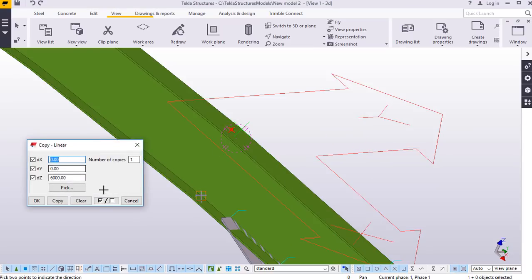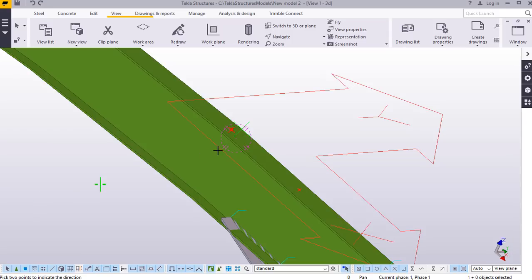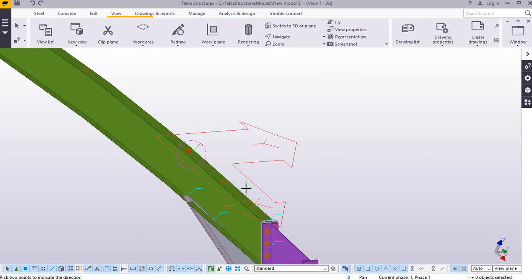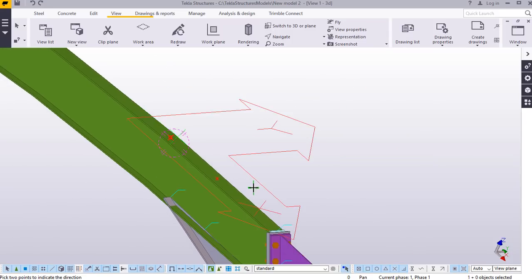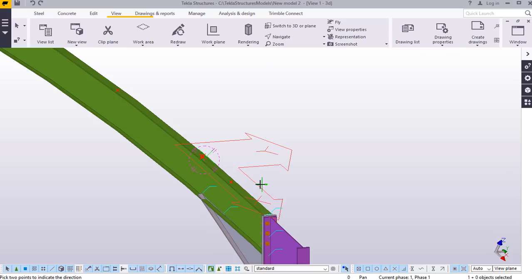Pick on that spot, right click, come to special copy, give it linear. Then from that we want to offset it along the x-axis, and the z-axis has to be 0 now. Now on our x-axis we want to offset this from this spot by 400 or 200. Let's try first of all 400 and click that. Apply and accept. Apply and accept. Still closer.